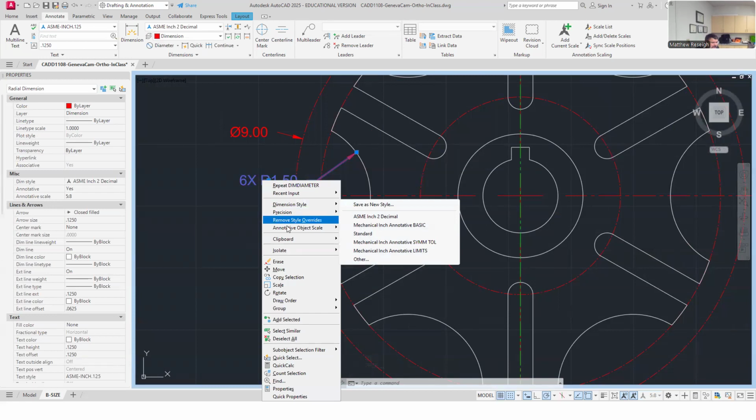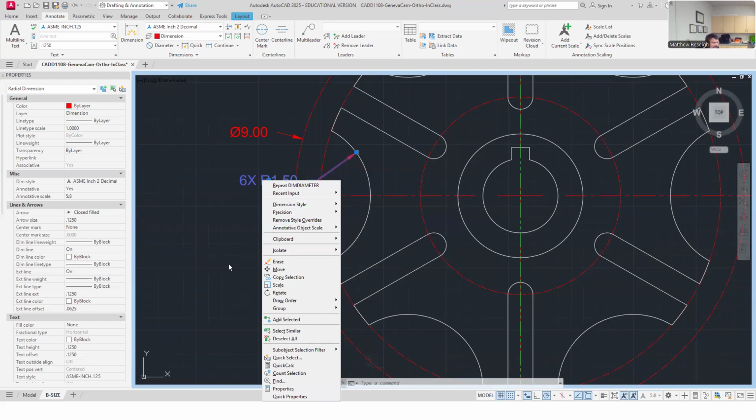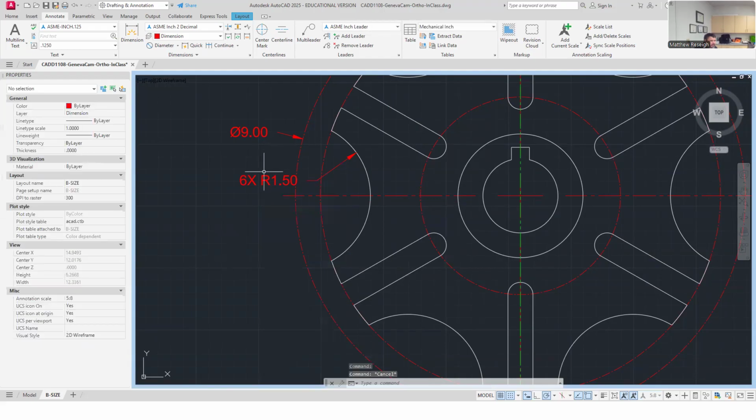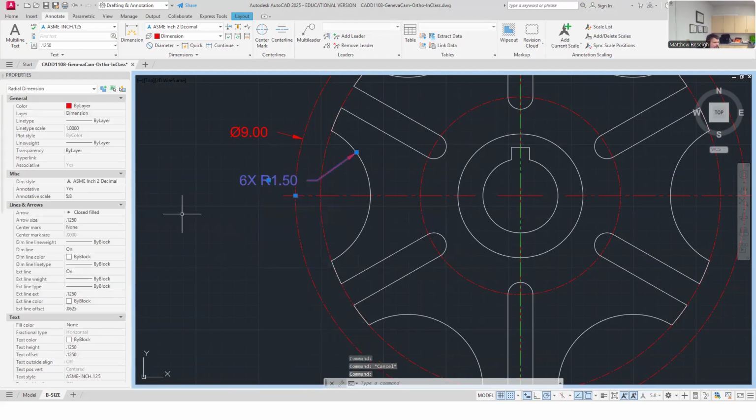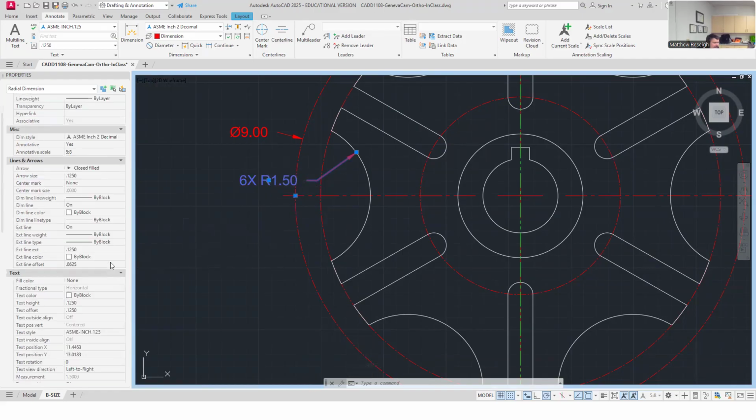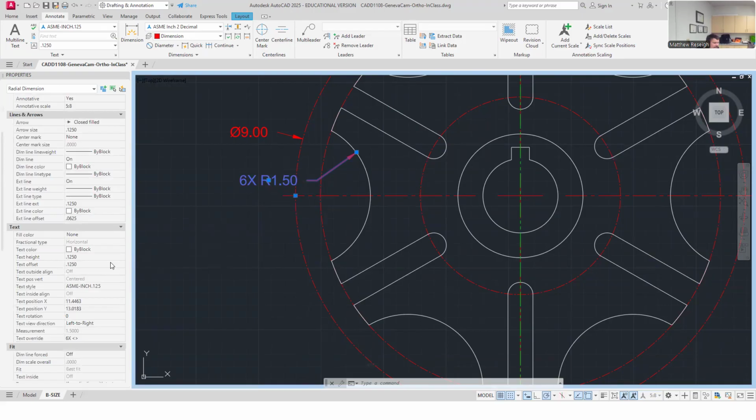The other thing I could add here, I don't know if I would change anything in my dimension style. I don't think so, but I could add, I think, the crosshair there. Because your dimension styles have the ability to add a center crosshair. It's just because I'm out here like in no man's land. I was just going to look through here to see if it has a quick toggle to add the center mark.